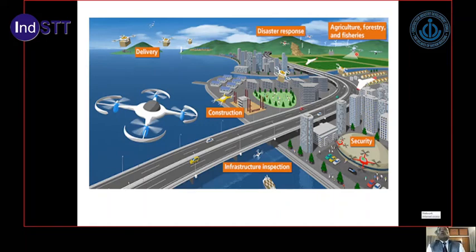This is topographical mapping. As civil engineers, when we survey some area and plan some infrastructure in the area, the first thing required is a topographical map. So you can do the topographical mapping, and with the help of this XYZ data, you can create a 3D model of the area. You can create the contours.